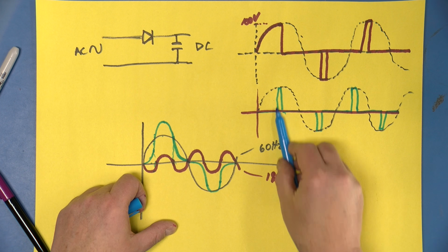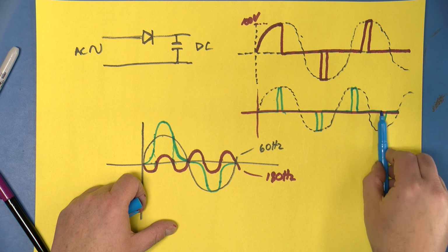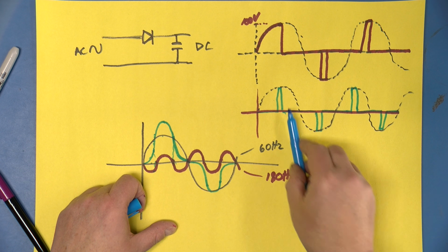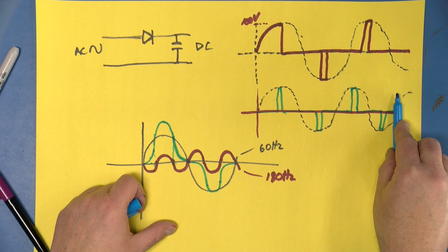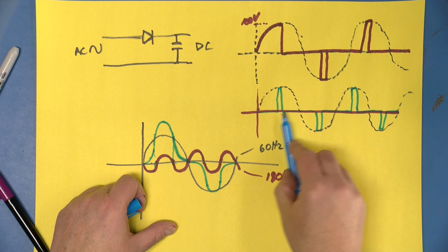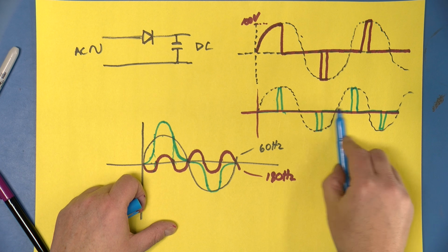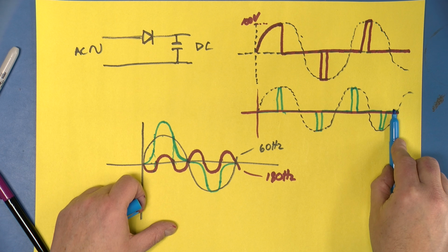The power company does not like it when we have devices using current in spikes of that nature. And this is also something that is included in the whole power factor thing, but it's really much harder to characterize because, as we're going to shortly see, the shapes of these pulses and stuff can vary quite a bit.